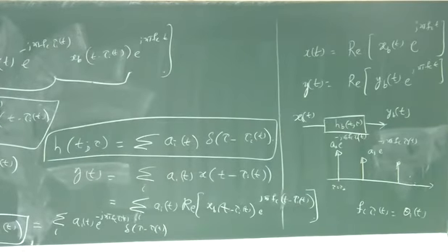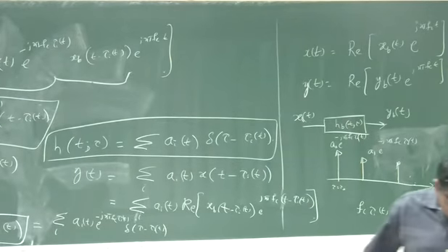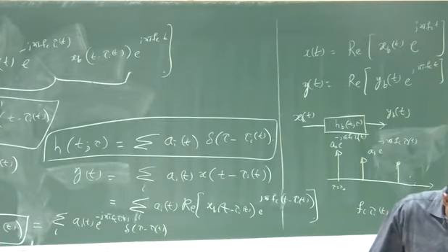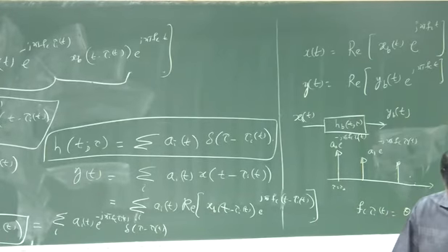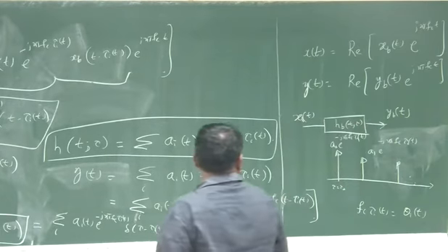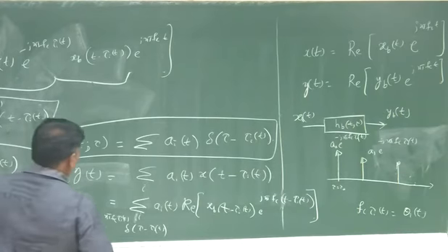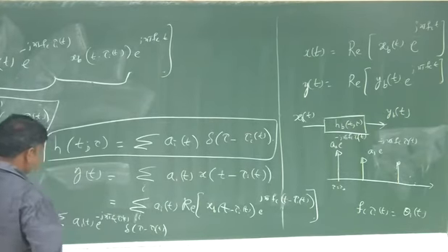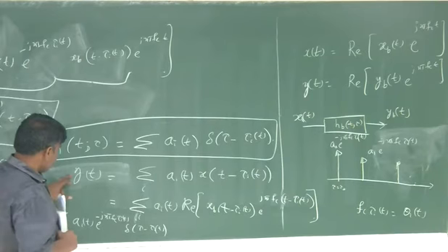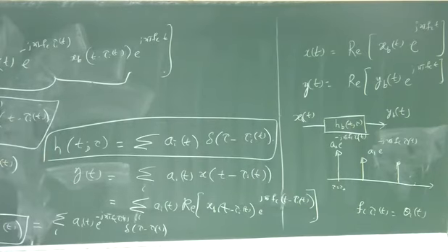It is a two-dimensional signal actually, in tau and the x amplitude, and the input signal is x amplitude. We are missing some signal? Nothing is missed here. There is an expression for yb of t. Yb of t is the summation over i of ai of t, if it is time invariant this part is gone, times xb of t minus tau i.